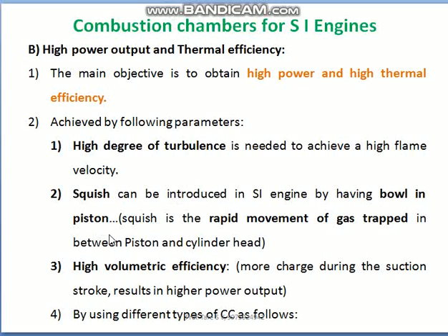Number 2 is squish effect. This squish effect is nothing but the rapid movement of gases that are trapped between the piston and cylinder head. Next is high volumetric efficiency. Volumetric efficiency, as I always inform you, is nothing but the breathing capacity of the engine. As I have mentioned here, high volumetric efficiency indicates more charge during the suction stroke, which results in higher power output.